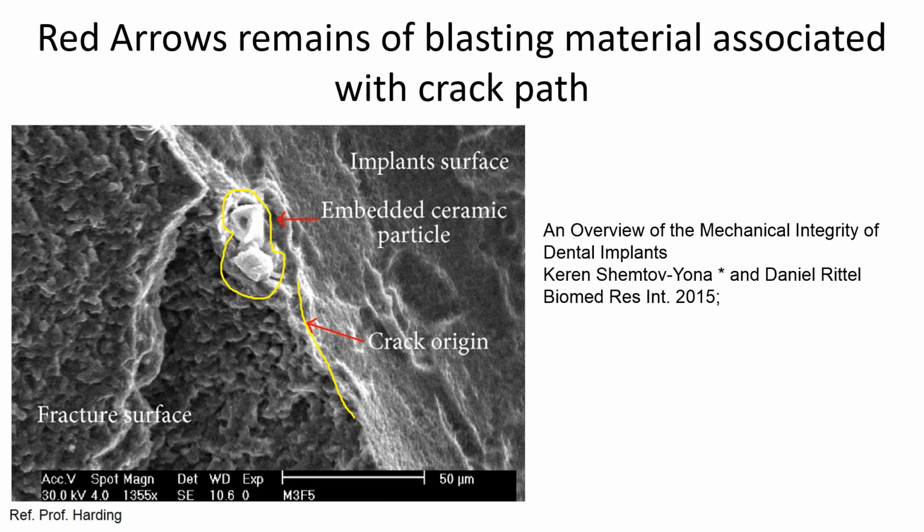Stresses will find a weakened area, they'll focus in on that area, and this is where the cracks originate from, where the blasting media has been left behind.